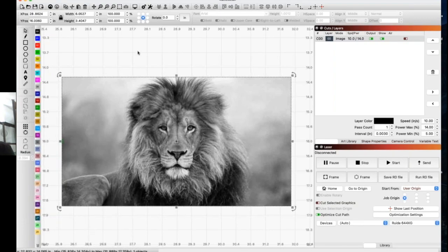Yeah, that's a good point. That's usually really where I make my determination, and then I play around. Can I get a little bit better quality if I'm trying to do an image on acrylic with halftone? Typically, yes, I can, but I can come very, very close. Like I said, it changes your DPI drastically. I can run with a high resolution lens or a 1.5 inch lens. I could run almost 1,000 to 1,200 DPI in halftone.